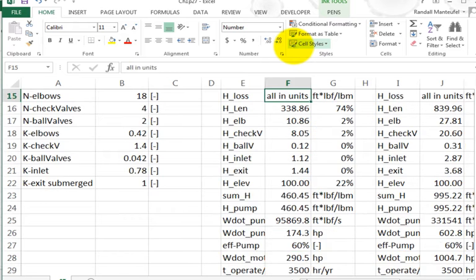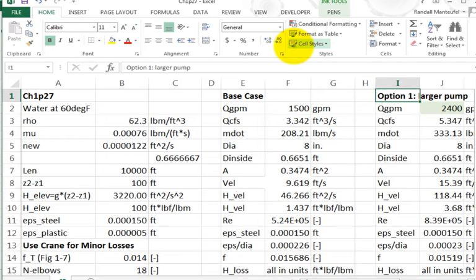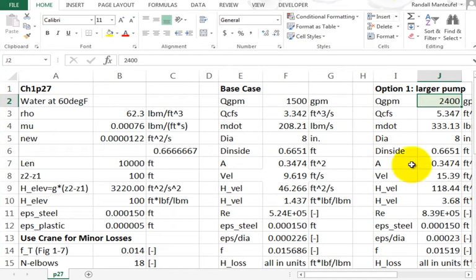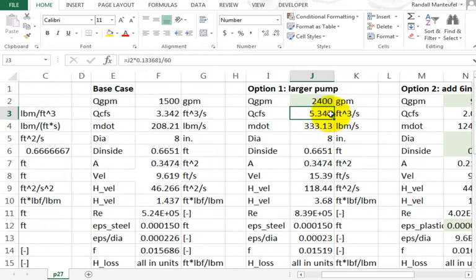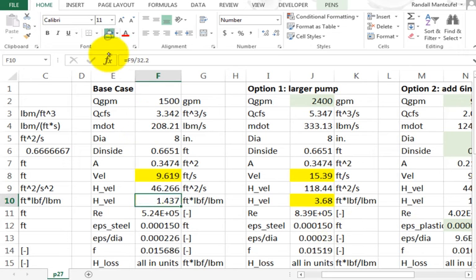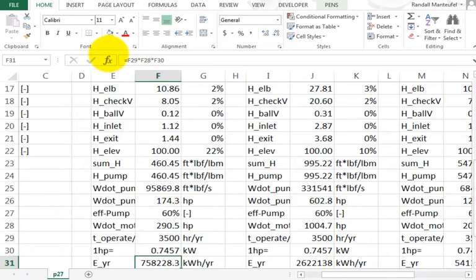You're ready to go to the larger pump. So you want to get this flow rate through the system, true? If you want that flow rate through the system, the CFS goes up, the mass flow rate goes up. You didn't change the diameter. Look at the speed now of the flow. Compare it to what it was. The velocity head is now a lot higher. See that? So now all of those loss coefficients are going to be more significant.